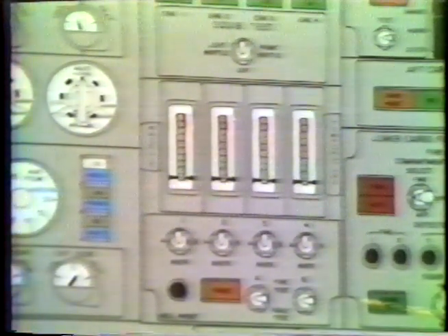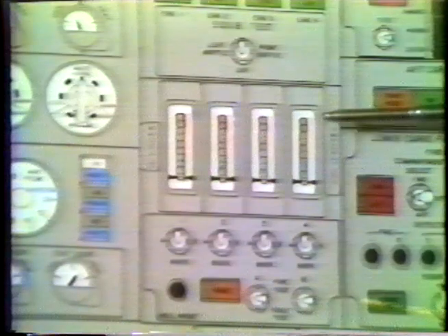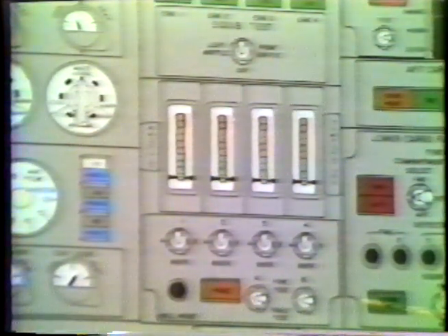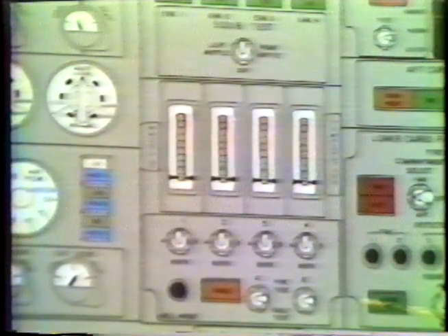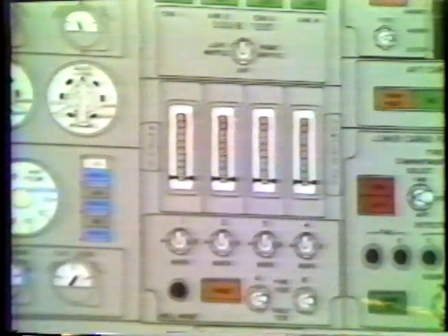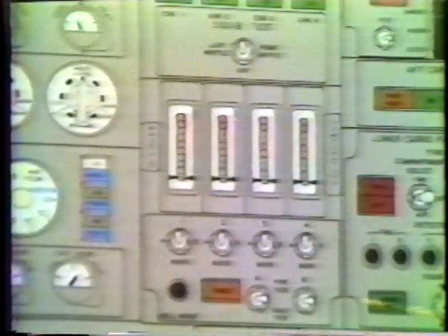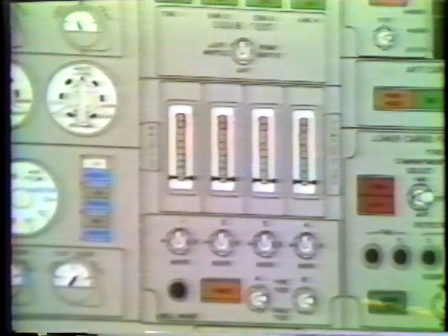If the temperature gets to the point where it gets into the red band, then an engine fire warning is activated with a fire handle coming on and the master fire lights coming on. And engine fire procedures should be conducted.